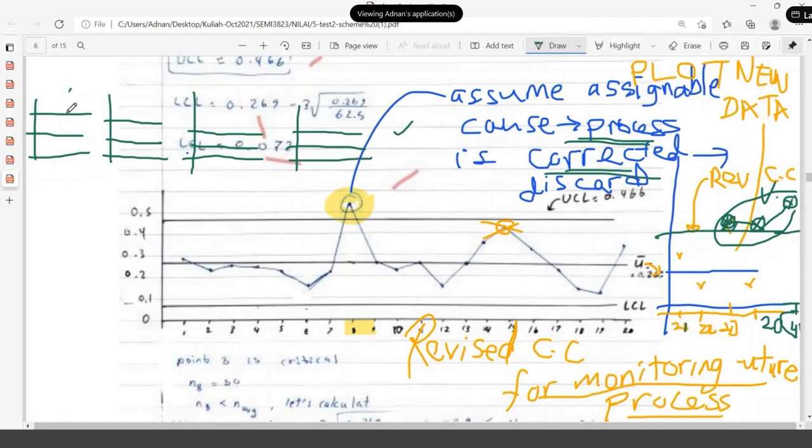You see that originally this range is big. The tolerance is very big. I mean the range, in this case, is the non-conforming unit earlier. So they keep reducing, because every time we get a point outside the control limit, it shows that the process is not stable.